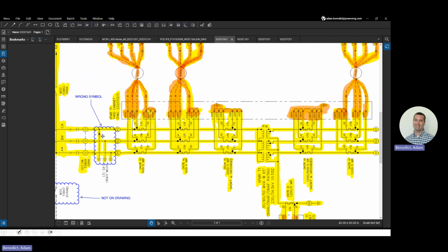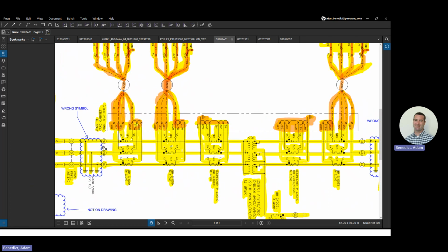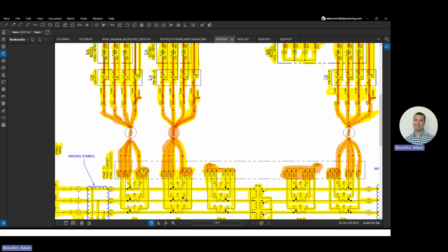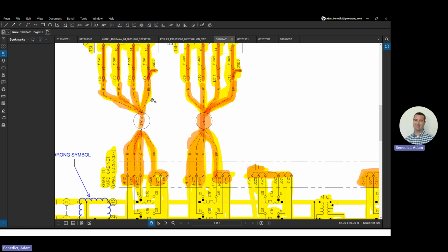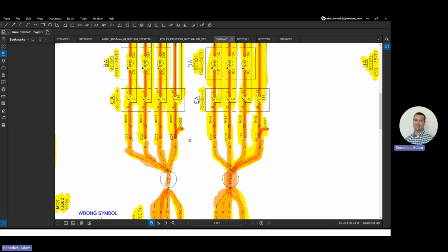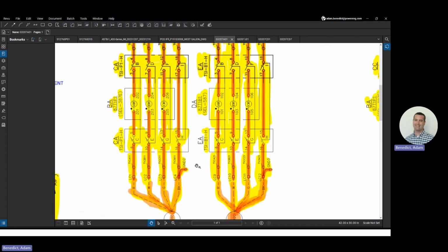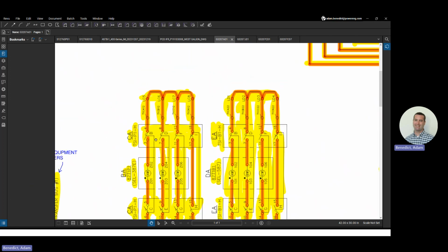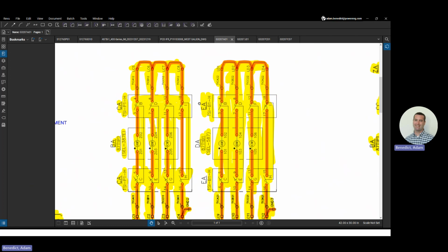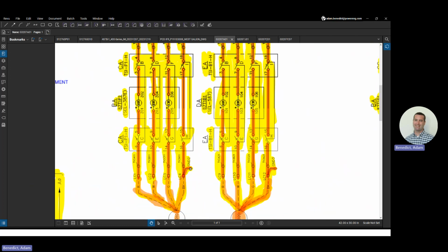Here they use the wrong symbol. These just look like grounds. I didn't do it. It was another consultant, but this just looks like they're grounding out the station, but this is actually LAs or surge arresters. So we fix that symbol, and then we're verifying H1, H2, H3 against the vendor prints. Looking for grounding. Here's where it's connected right in the first panel inside the control house. You're making sure you got shorting CTs here. This is all connected, and then there's a return back.